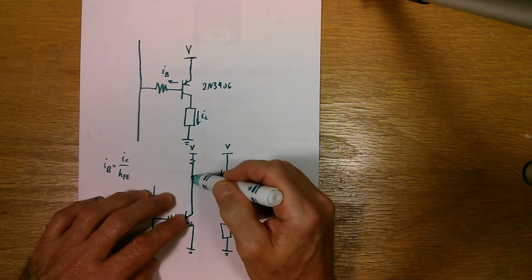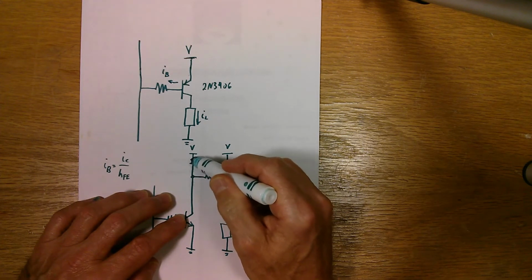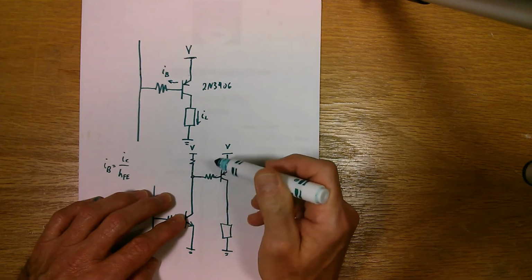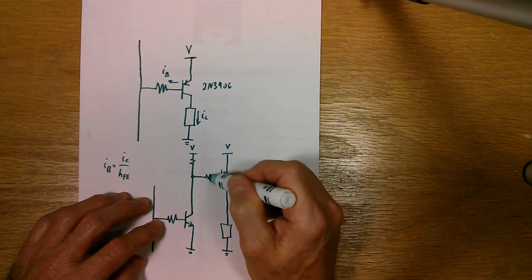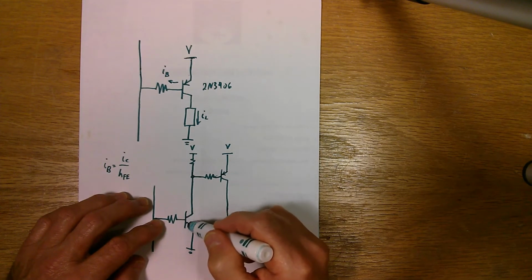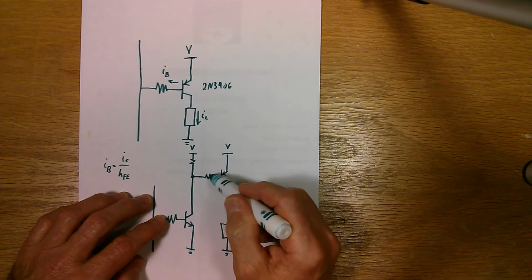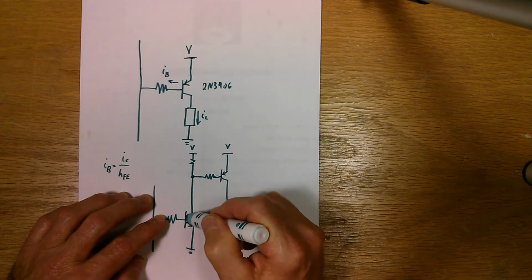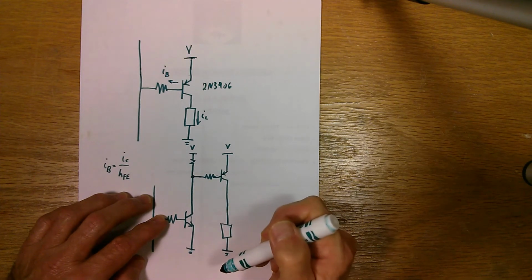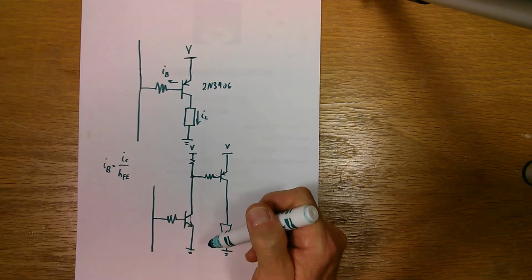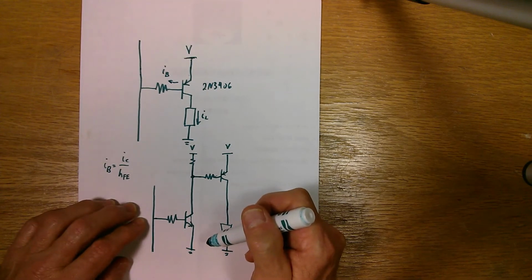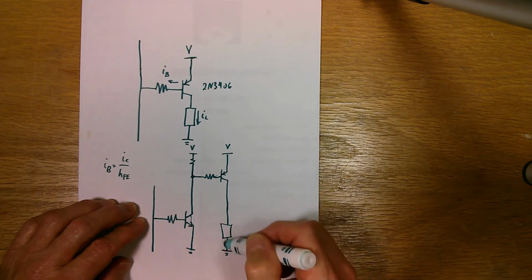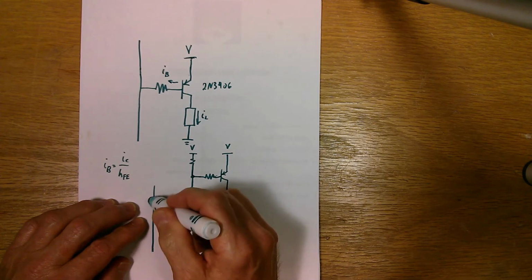So there's no current flowing through here, no voltage drop across that. It pulls this pin up here and it turns off the base current. To turn on this stuff, I need to turn on this transistor, which draws this point down to ground and draws current through the base and emitter of the transistor. So it kind of inverts the signal as well. To turn on this load, I have to raise this high.